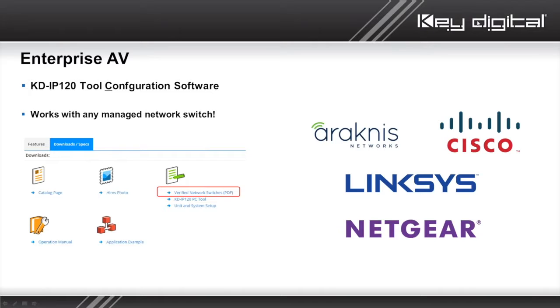And on top of that, we've even heard that those wizards, if an additional transmit or receive unit is added to your system, which is, you know, one of the benefits of a video over IP system, right? Because it's flexible, it's not a cookie cutter, as we mentioned. If you add a transmit or a receive, well, then those wizards are likely to jumble up your IP addresses for all of your units, and then you'd have to reprogram your system.